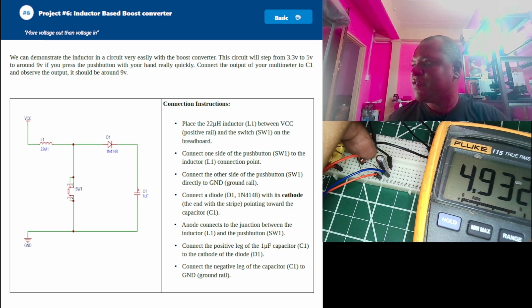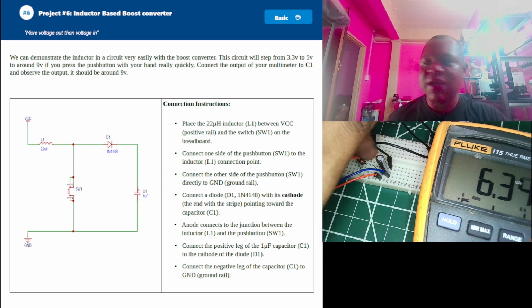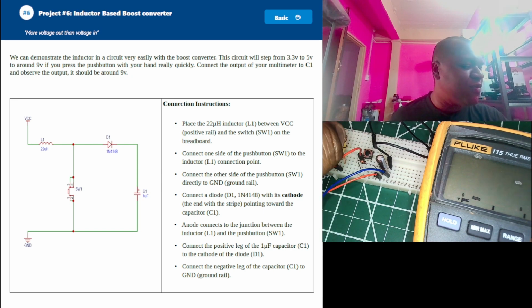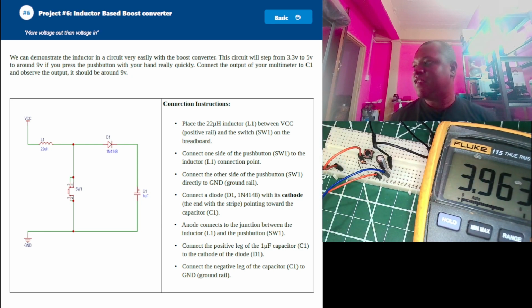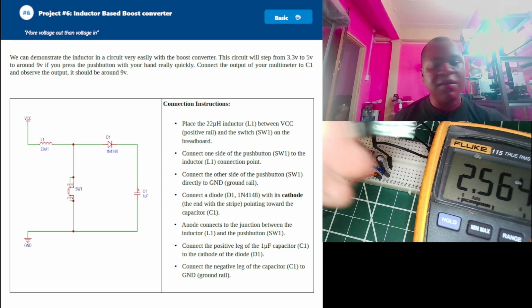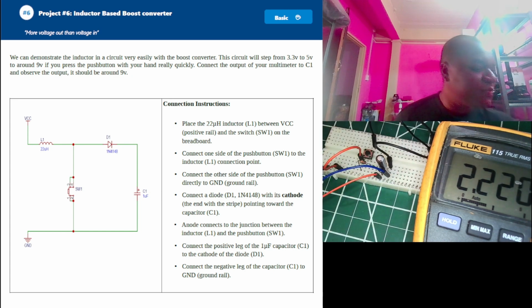we've closed it fast enough. We actually see we get this jump, and it could jump all the way to 9 volts. And I want to share why I need tight winding, because this isn't really too tight. That's just the capacitor holding charge and quickly discharging. If we use a shielded inductor, like when I showed you, it's much better designed.